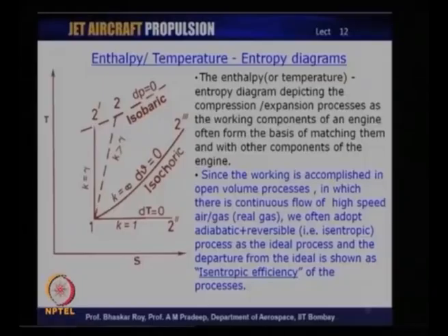In case of the compressor, it is air, and we often adopt the so-called isentropic process as a reference or a benchmark to find out the goodness or badness of a real compression process. This comparison between the ideal, isentropic compression process and the real compression process is referred to as the isentropic efficiency of the process.